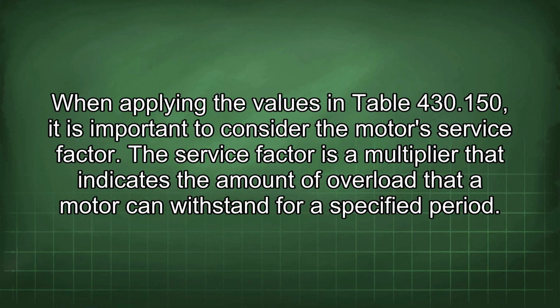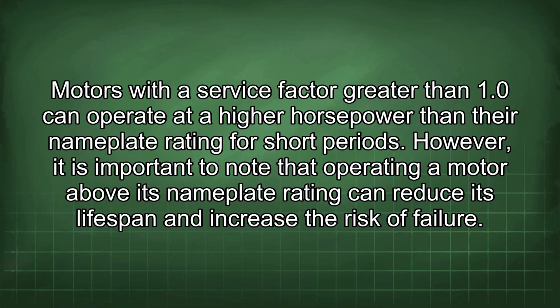When applying the values in Table 430.150, it is important to consider the motor's service factor. The service factor is a multiplier that indicates the amount of overload that a motor can withstand for a specified period. Motors with a service factor greater than 1.0 can operate at a higher horsepower than their nameplate rating for short periods. However, it is important to note that operating a motor above its nameplate rating can reduce its lifespan and increase the risk of failure.